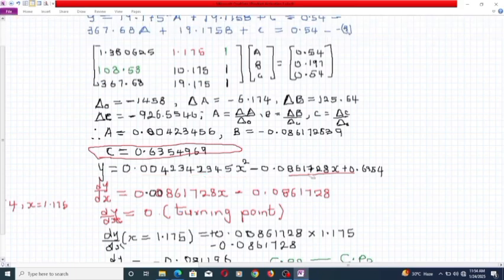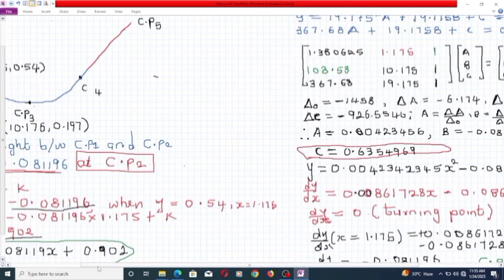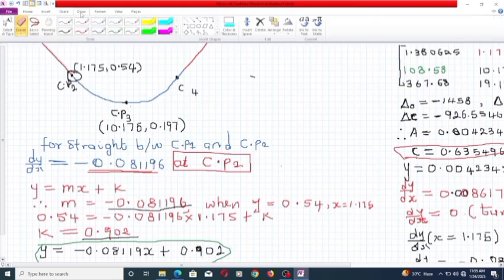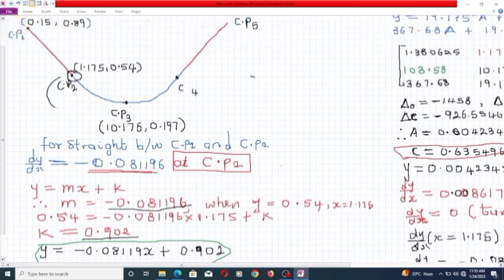Now with this equation we can link it with the equation of a straight line, as the profile is expected to have a straight portion from this particular entry point. So at this particular point, we are linking this part of the profile down to control point 2. At control point 2, we can begin to look at how the parabolic portion connects to the straight portion. So this portion will go into the recess of the beam.